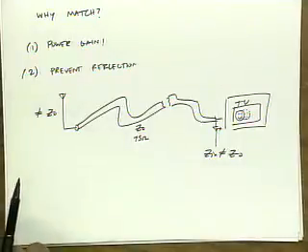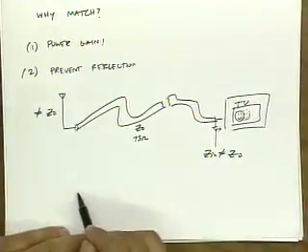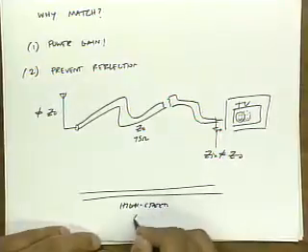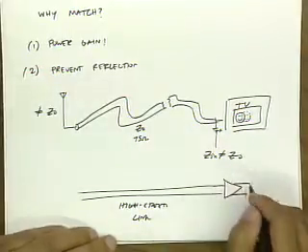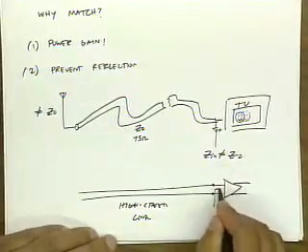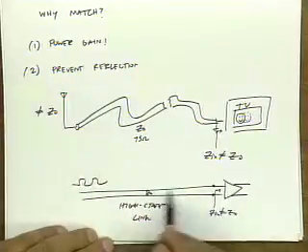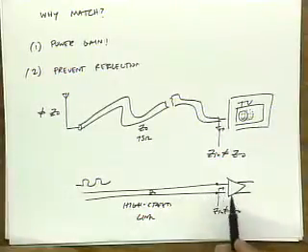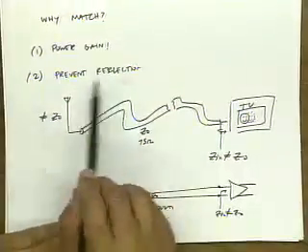Another example is a data communication system. If I'm sending high-speed bits, let's say I have a high-speed link, and let's say I have an amplifier at the end of the link. If the input impedance is not equal to Z0, then this data gets reflected and actually produces intersymbol interference. So it gets harder and harder to correctly detect these bits. Okay? So there are many situations where we terminate to prevent reflections.